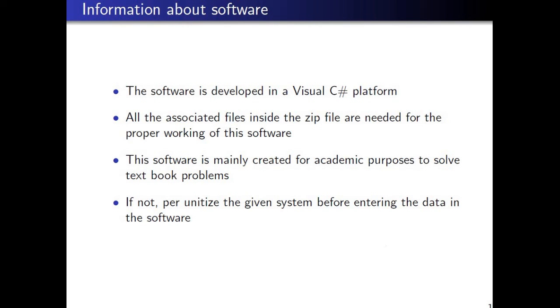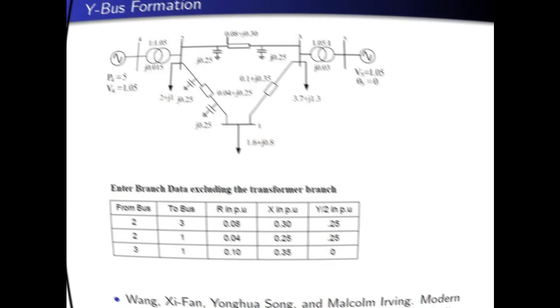This software is mainly created for academic purposes to solve the power system textbook problems. We know in most of the textbook problems, the data are given in per unit parameters, but if not, we encourage the students or the users to per unit the given system by choosing proper base values, MVA and voltage, before entering the proper data in the software.